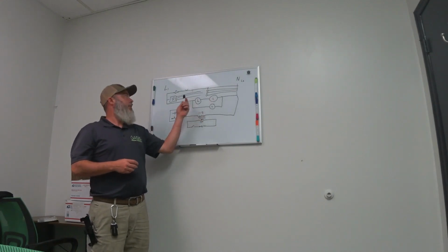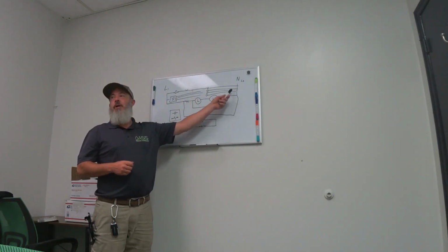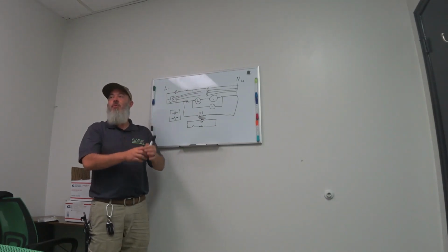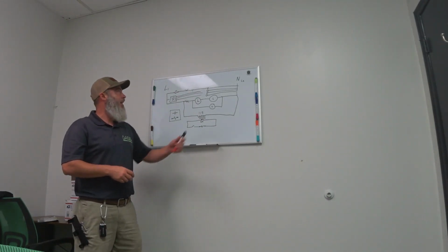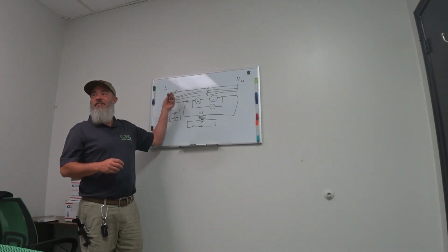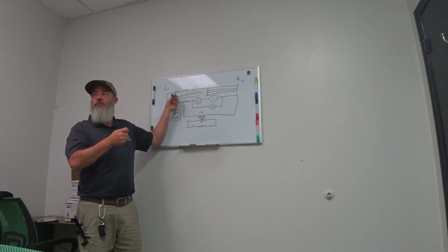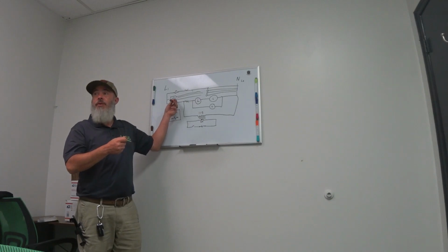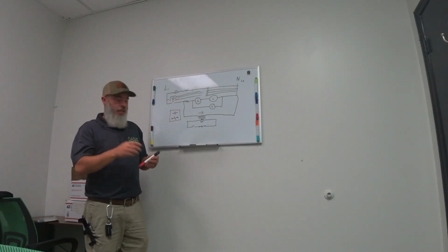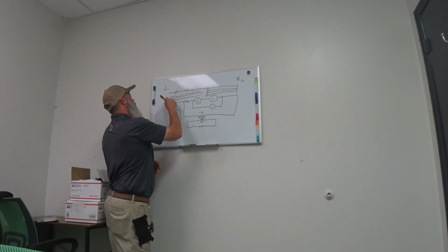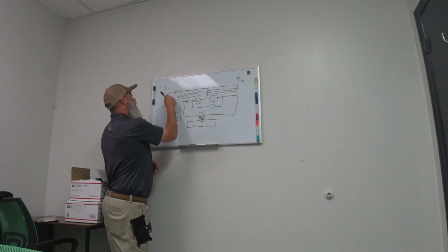Whenever you're testing, usually you'll find a bundle of white wires together. You put one lead in there, and then you come over here and start testing the other side of it with your other lead to say, okay, we've got power there, power there, power there. We don't have power there. Oh, we're supposed to. Why don't we have power there when we're supposed to? So that's how we do troubleshooting electrically.